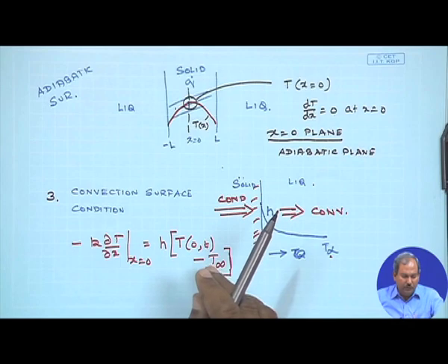So, we would use the conduction equation to start with, in the appropriate coordinate systems with appropriate boundary conditions, and quickly try to solve and see if we can get the temperature profile of a solid object which is experiencing conduction. Initially, we would restrict ourselves to the case of steady state, where the temperature could be a function of x, y, z, or r phi z, or r theta phi, but it is not a function of time.